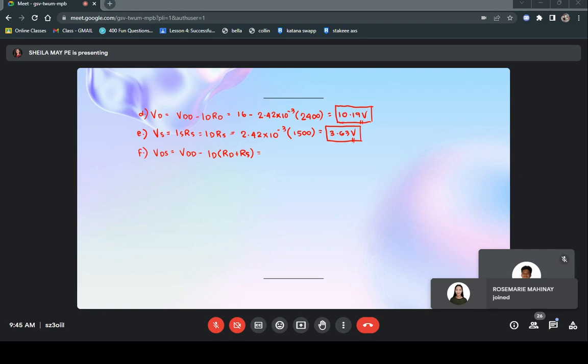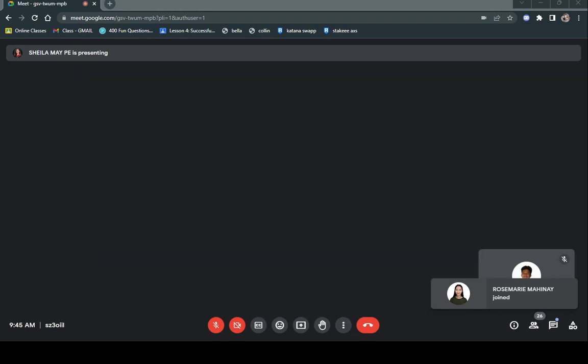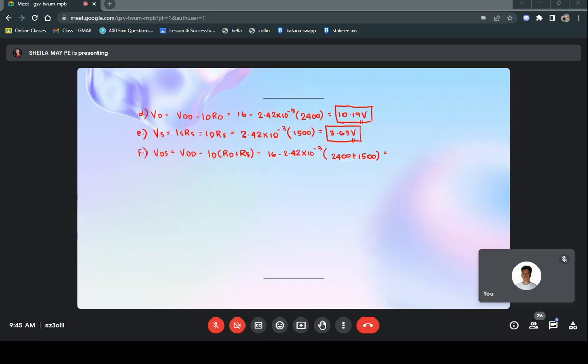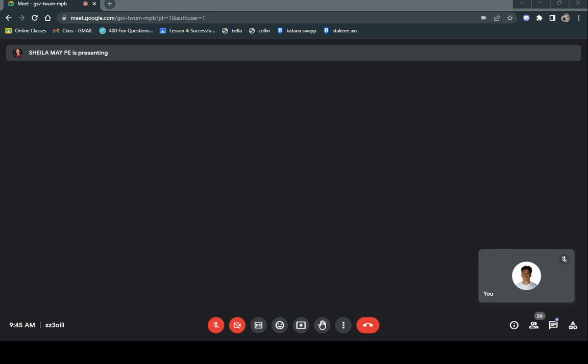So VDD is 16, ID is 2.42 milli, RD is 2,400, RS is 1,500. So basically VDS is just 6.56